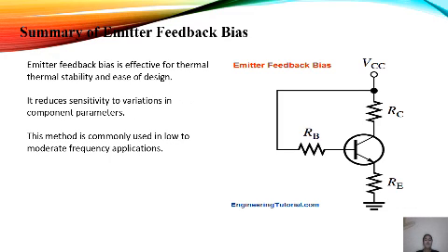Summary of emitter feedback bias. Emitter feedback bias is effective for thermal stability and easy to design. It reduces the sensitivity to variations in component parameters. This method is commonly used in low to moderate frequency applications.